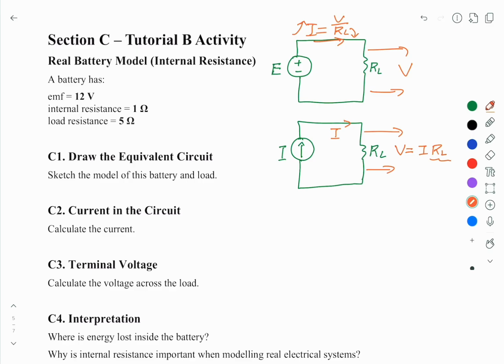And we also know the power supply we use in the laboratory behaves close to the ideal voltage source, as long as the current is not bigger than the maximum current we set, or the maximum current the power supply can provide. And also the power supply used in the laboratory can behave like an ideal current source, as long as the load resistance is not too big.